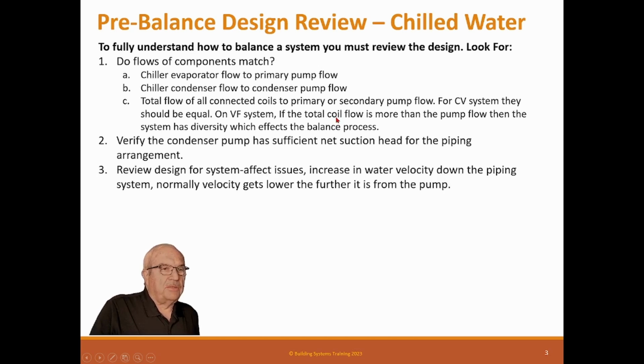Verify the condenser pump has sufficient net suction head for the piping arrangement. So remember that all pumps have to have a certain amount of pressure on their suction to perform correctly. And so you have to check that. Normally it's okay. The only place that's really a problem is on cooling tower suction pumps. It should never be a problem in a closed system.